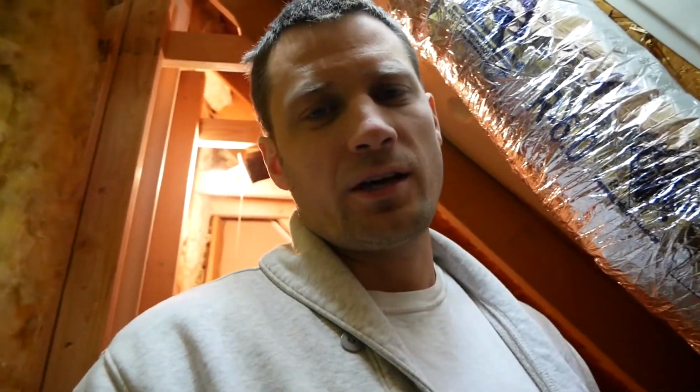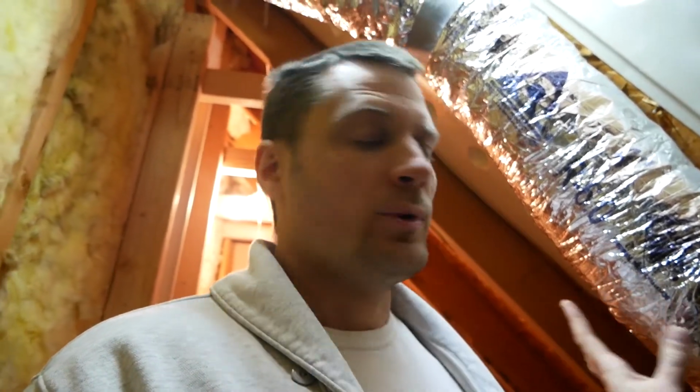If we didn't hear the sound coming out the soffit vent there, what we'd want to do is go outside, check it out ourselves, up on a ladder, put our hand up next to it. We definitely want to have some air exiting there. If there isn't any air exiting, some things you want to check out: is the baffle itself stuck in the soffit vent? Do we have some kinks in the ducts? And then the fan itself has its own little baffle, and if that gets stuck, it could prevent airflow, so you'd also want to check that as well. So just a couple things to troubleshoot if you're not testing properly.